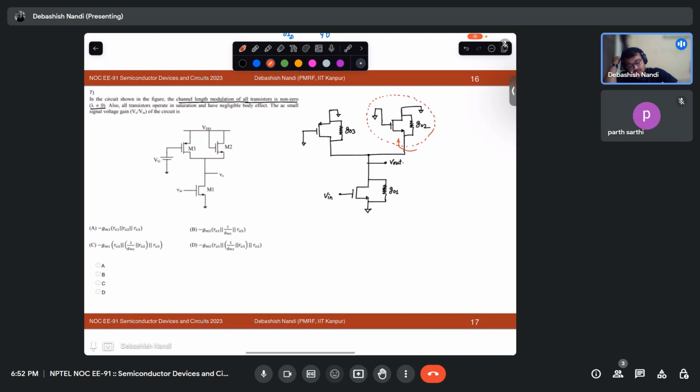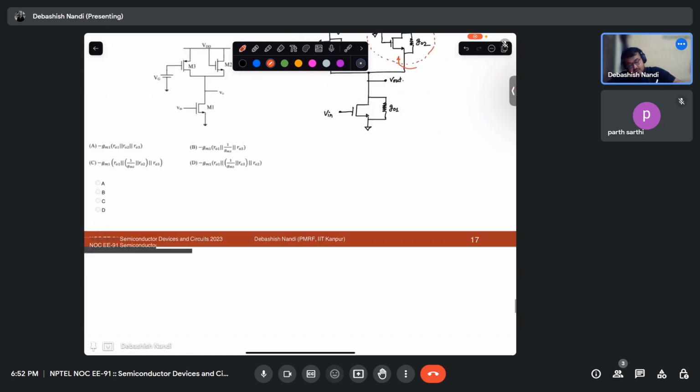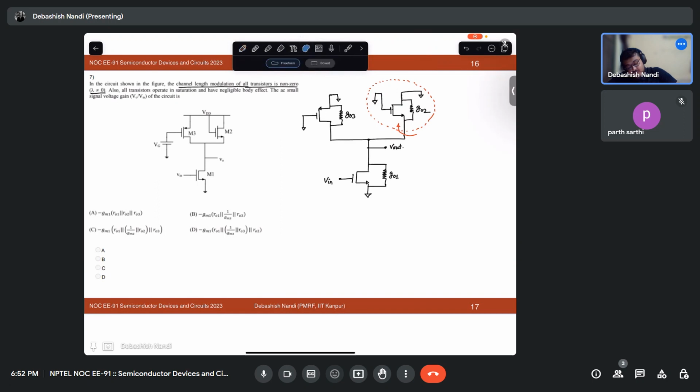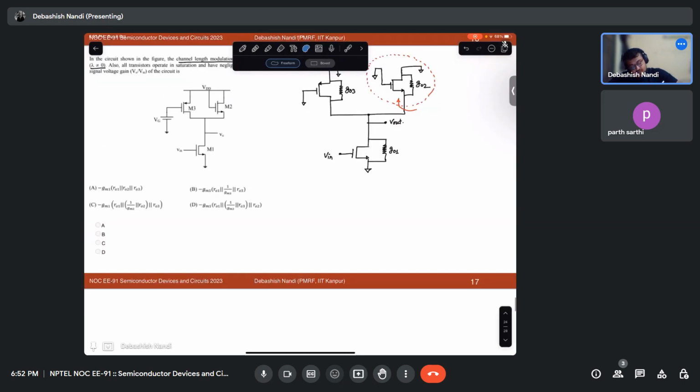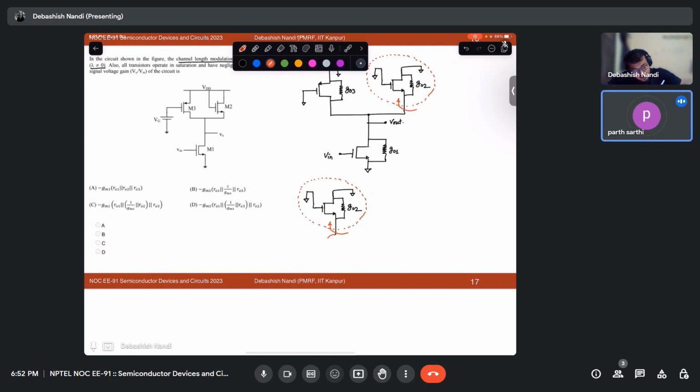First, let us take this contraption. So what is the impedance looking in? How will you find that out? Norton's equivalent? No, there are much simpler things. You don't go to those steps, it will take time. You apply a V test, and you measure I test.